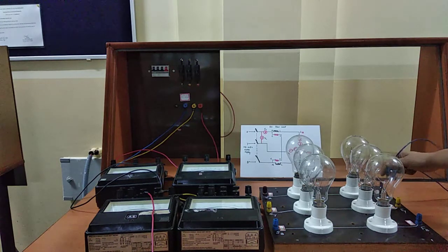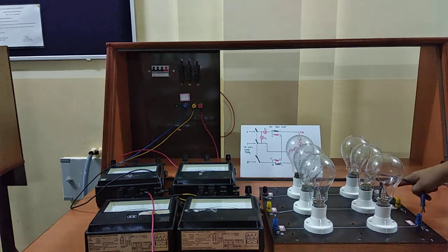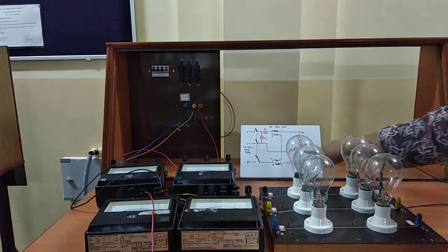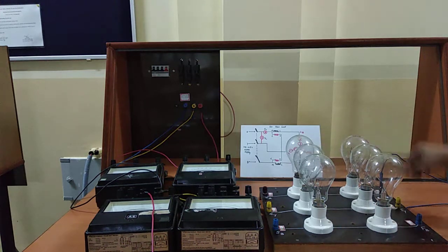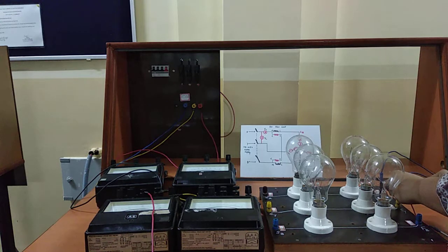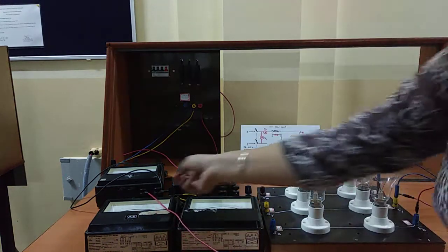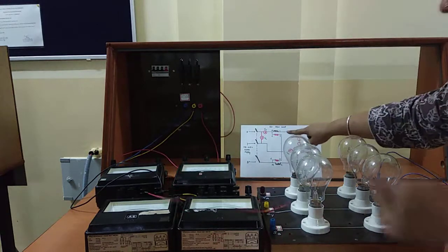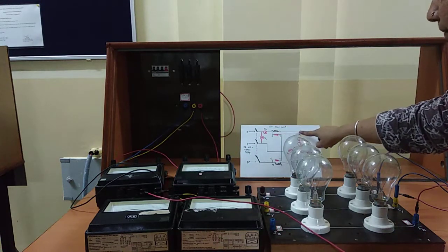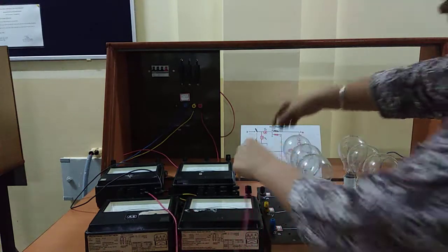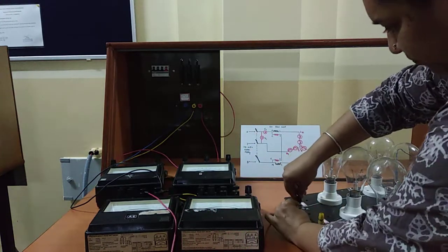Since in star connection all the similar ends meet, I'll be choosing the end points to meet at a point as indicated in the circuit diagram. Like we have FR, FY and FB meeting at a point. FR will meet FY and then we have FY connecting to FB. Alright, so the star load is now ready. Now from the wattmeter, the end where we had the load connection, from here it will come to the point SR. So from here it is connected to the point SR.